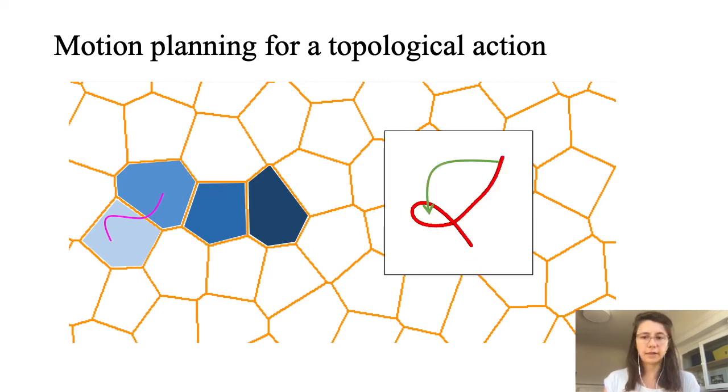So we limit the space of robot motion trajectories to splines with 3 control points. One example of such a spline is shown here in green. The robot will grasp the rope at the first control point of the spline, move along the spline, and release the rope at the third control point. The choice of letting the robot move along these splines reduces the long horizon RL problems to a bandit problem, and therefore avoids instability issues with common RL algorithms, especially during training.